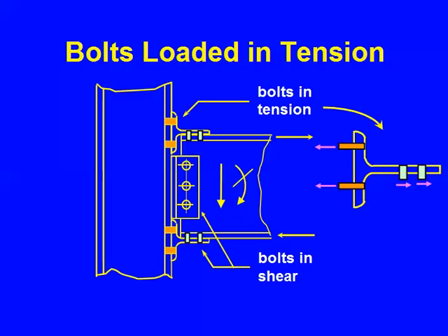And we would start by resolving the moment into a force couple. If you'll watch, it will appear before your very eyes. That set of forces acting at the level of the flanges is a good approximation of the moment. In an I shape, most of the moment is carried by the flanges. Remember that? Most of the shear is carried by the web. I mean, that's supportable. It's not just somebody's idea.